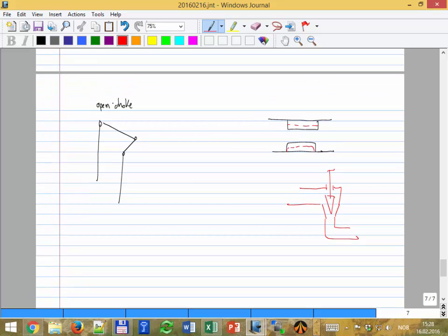So the comment was that an open choke means that maybe this system was operating with a bean choke, also called a positive choke. Maybe they were just changing over time, and at the end they just left it open. They didn't put anything inside. They say now this system is operating at depletion. Then I'm going to stop here, and this is P suction to the compressor. The compressor, I'm going to remove it, and here I have P discharge.